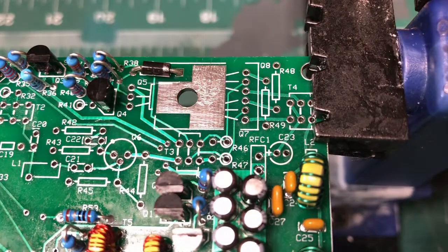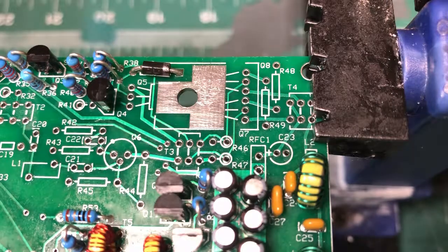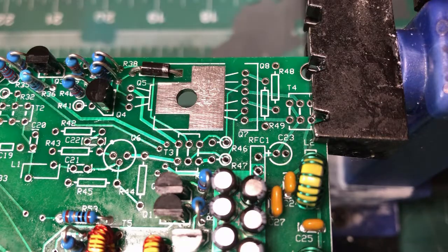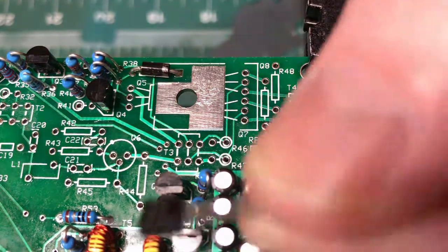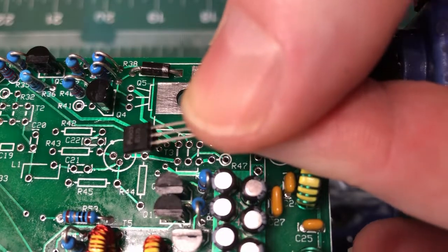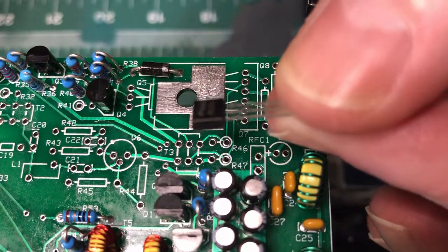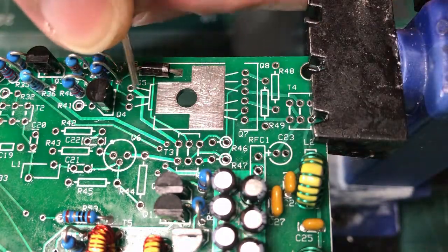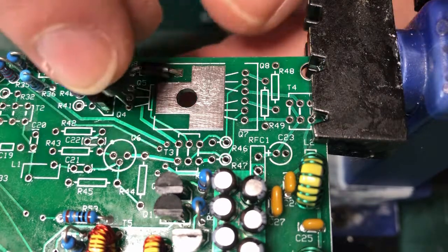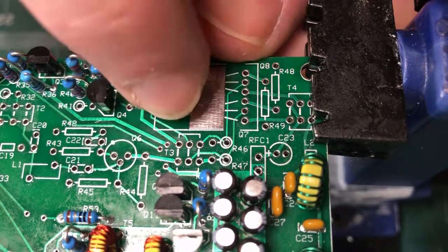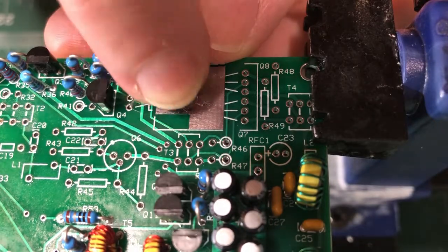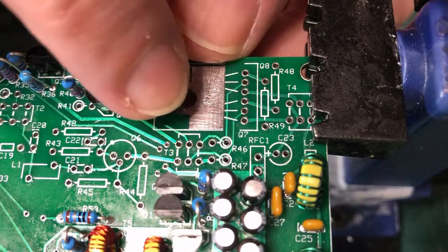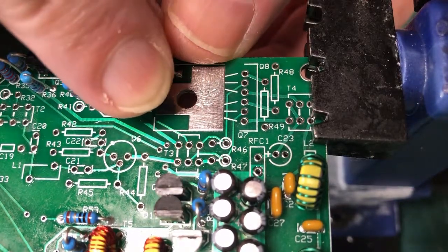So I thought I'd just show the installation of the FET. This is a B170 FET here. Let me just see if I can get it underneath the camera. And they are static sensitive, so you've got to make sure you ground yourself before touching them. And with this particular configuration, they need to be bent backwards so that when the heatsink goes on them, which they do get hot, it fits flush.